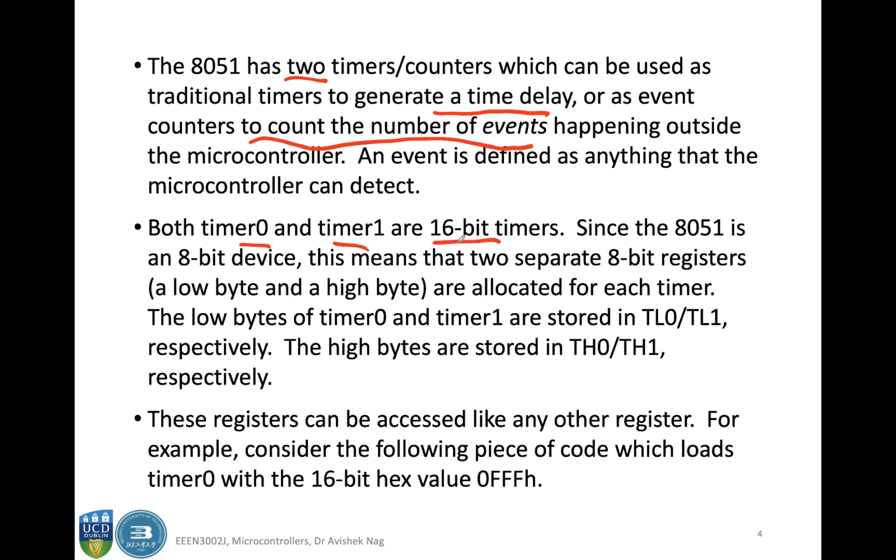Basically this means that they can count from 0000 hex to FFFF hex, so in decimal equivalent between 0 to 65536. Okay, so they are 16-bit timers, but the 8051 is an 8-bit device.